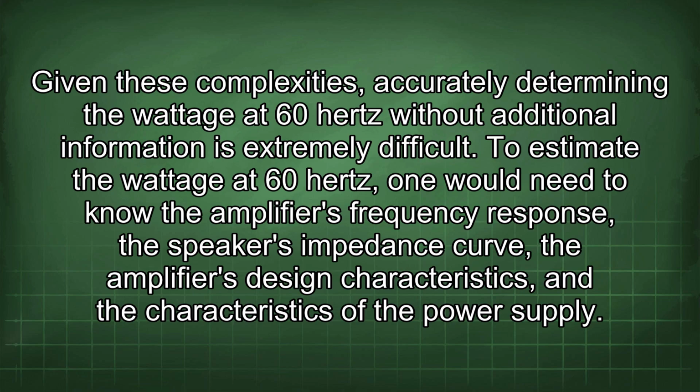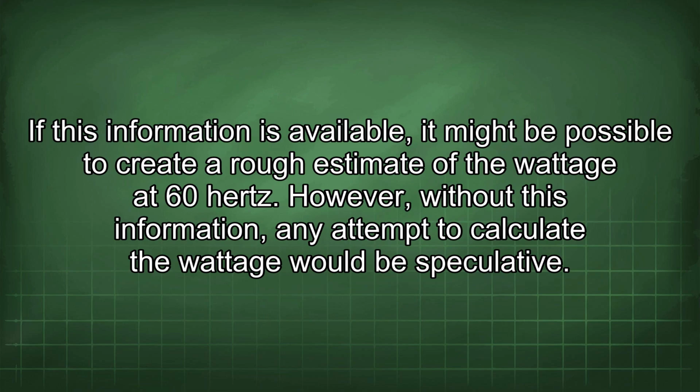Given these complexities, accurately determining the wattage at 60 Hz without additional information is extremely difficult. To estimate the wattage at 60 Hz, one would need to know the amplifier's frequency response, the speaker's impedance curve, the amplifier's design characteristics, and the characteristics of the power supply. If this information is available, it might be possible to create a rough estimate of the wattage at 60 Hz. However, without this information, any attempt to calculate the wattage would be speculative.